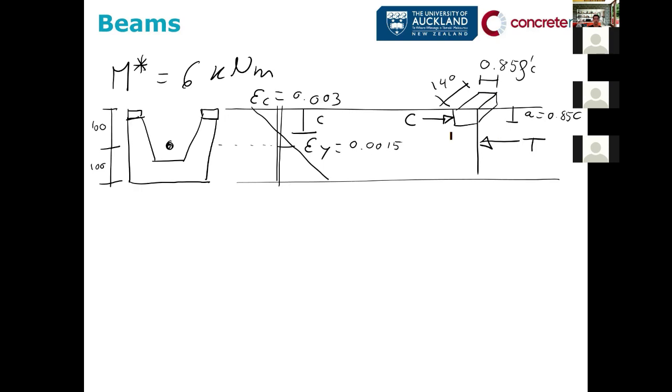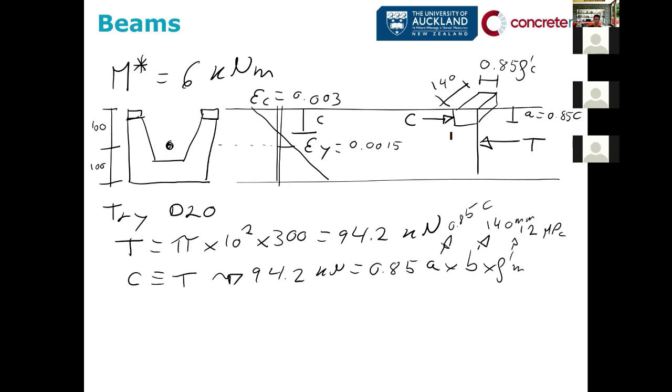I'm sure you know this for years now, but it's basically the basics of any design, right? We can start with D20, for example. We can calculate the tension force. It's just the area times Fy. We have 94 kilonewtons.